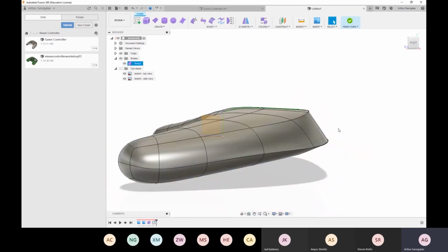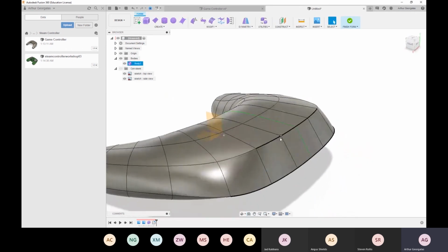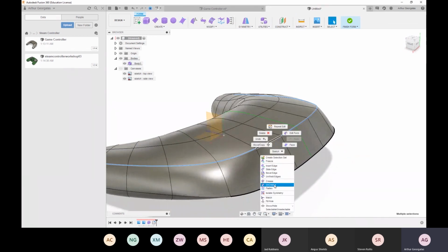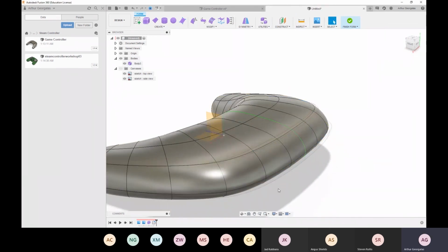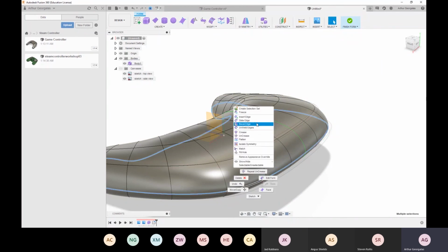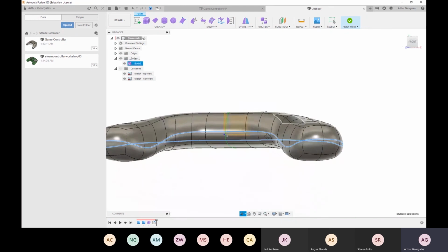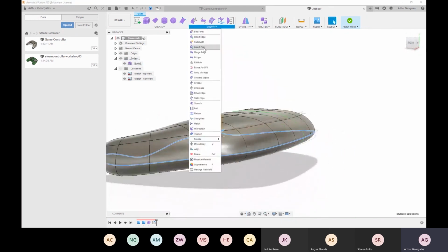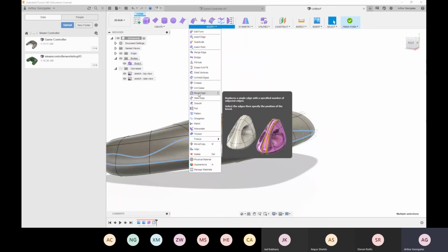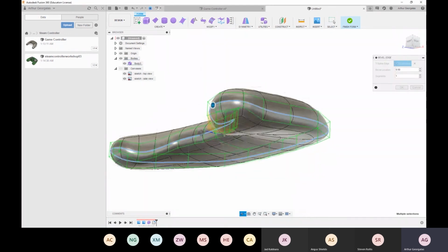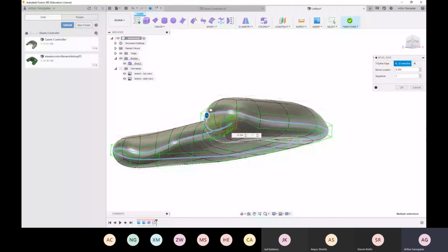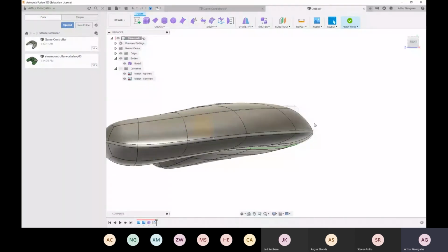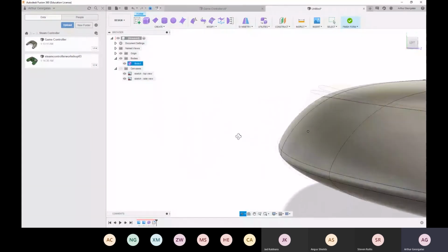If we were to try and do this in here, one way we can do it is get rid of these creases by adding more lines. So if we double click this, it selects that whole loop all the way around. And we can insert an edge, or we can do something like a bevel, which inserts a line on each side of it. Again, you should play around with these tools. So we can make that really nice and tight. And it looks quite good.